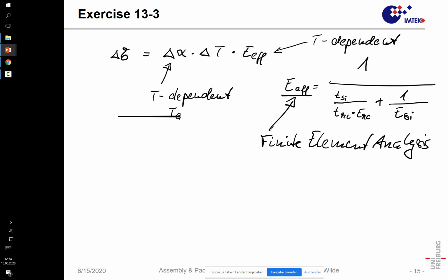Okay, that's how we compute stresses. So more or less, we have some conditions from mechanics. We have the thermal expansion. We have the linear elastic behavior. We have the equilibrium of forces, and we maintain a continuous body. And in that way, we got sufficient information to solve this stress-strain problem.